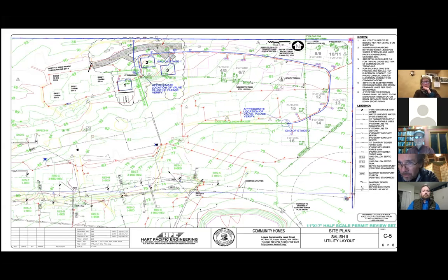And one other thing on all of that, especially during these progressive developments, you want to make sure you get good as-builts. It's really worth it to do that. And an as-built, so here we have, right, this is a site plan, and a local engineering firm has done it. But I know for a fact that when we came out of here, we moved this line up here.